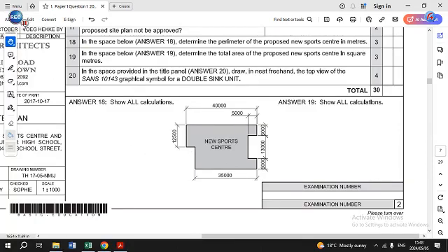So if you look at the calculation, we're going to start with this side here, which is going to be 40 meters, and there's the 40 meters, and I'm going to tick that 40 meters, and then you go down here, which is 12.5 meters, tick there, that we have that one. This we said is 5 meters, which is that 5 meters that you see here, and then we go down, which is the difference between the 25 meters here and the 12.5, which is another 12.5, because 12.5 and 12.5 gives you this total of 25 meters.